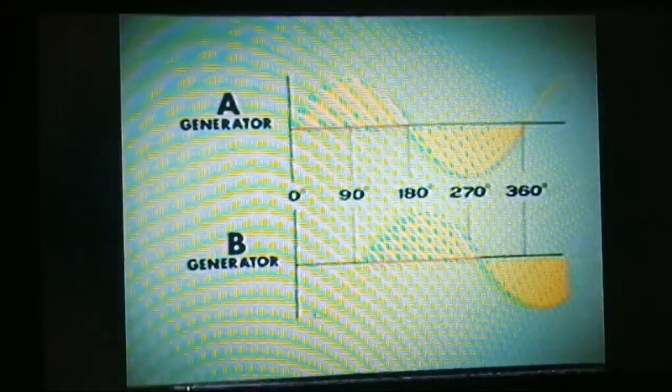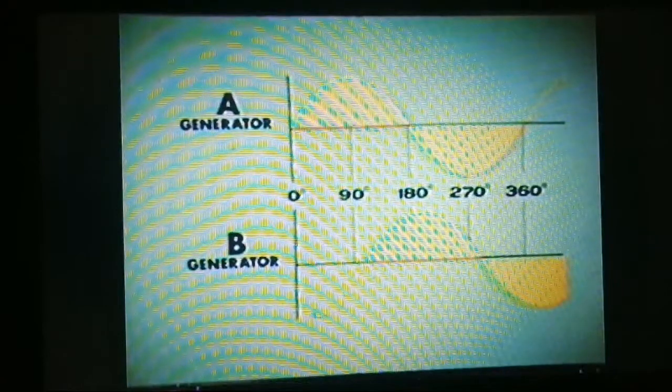These units will be labeled A, B, and C, and notice that on each, poles are in the same position, but coils B and C have been moved so that the three are equally spaced around the circle. Since B coil is located 120 degrees past A coil in the direction of rotor travel, its voltage pattern or sine wave will be 120 degrees later than the voltage pattern from coil A. But since the generators are the same and rotation rates are equal, the sine wave of each will be identical.